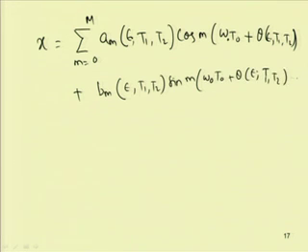Here omega 0 is nothing but the square root of alpha 1. In comparison to our original harmonic balance method, where we have taken Am and Bm to be constant, here we are taking Am and Bm as functions of epsilon and the time scales. In the method of multiple scales also, we have taken these coefficients as functions of different time scales only.